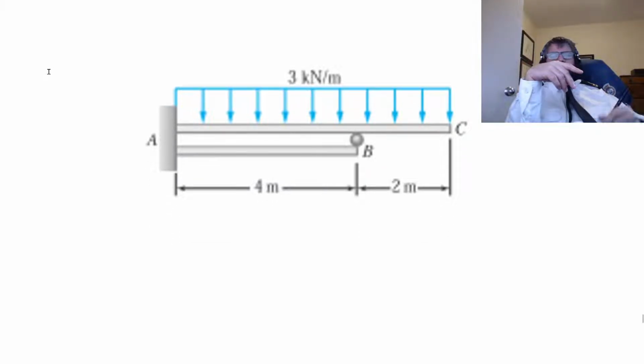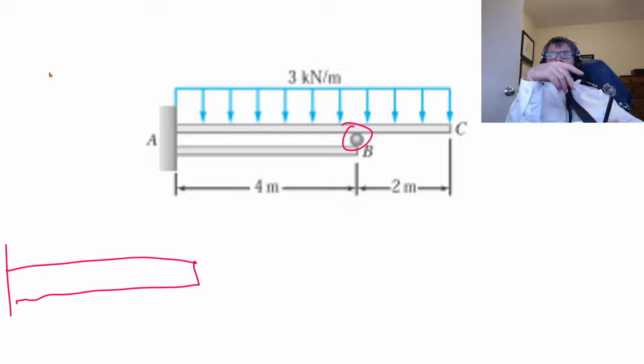Again, our compatibility conditions are going to be based upon the contact point here. So essentially, for AB, it's going to be pushed down. It's going to have a certain amount of displacement B, and the magnitude of that force By is going to be proportional to that displacement.